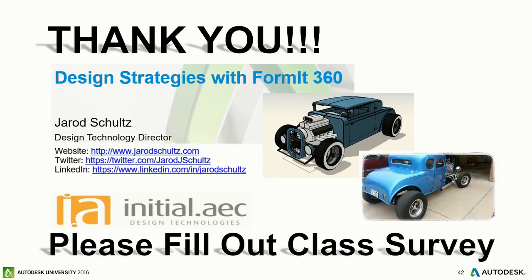For location mapping between Formlt and Revit, Revit has the origin, the survey point, and the project base point. How is Formlt thinking about location? Is it just using one of those to align with Revit, or does it have all that stuff going on in the background? No, it's not.